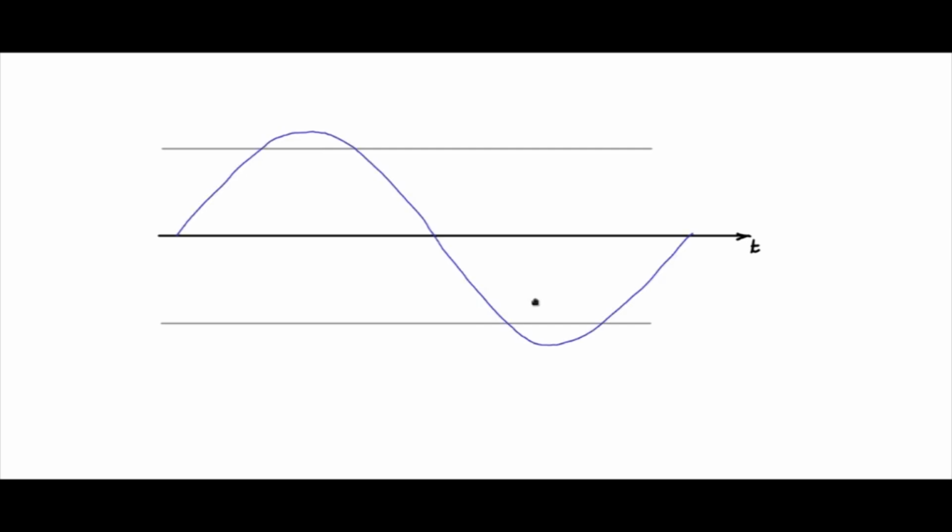Now, let us say I have a sine like this. It is shooting over more than 100%. Can I modulate this? You will see that once this 100% modulation is reached, it goes to overmodulation. It is no longer linear and a proper PWM wave will not be obtained. Now what we can do is, let us say I have this third harmonic. Okay, this is the third harmonic triplen, and I will use this. I will subtract this from this.